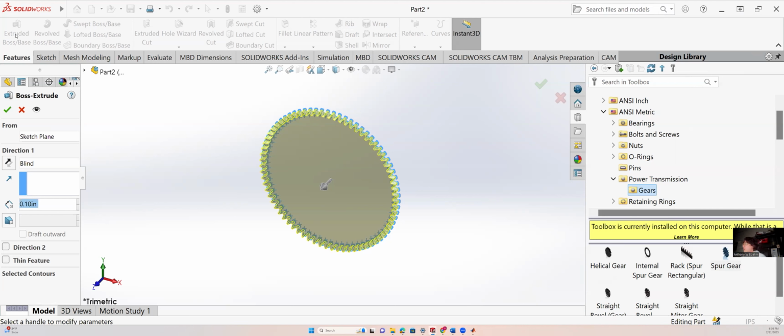So that is what I'm going to go for when it comes to the overall width of all these parts. For this middle gear in here, hopefully you guys can see, the middle gear is a compound gear. It has a smaller gear on the back and a bigger gear on the front. The smaller gear on the back interfaces with the crank gear, which is the one that you rotate in order to spin the fan.